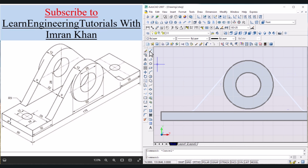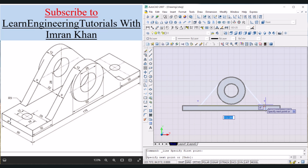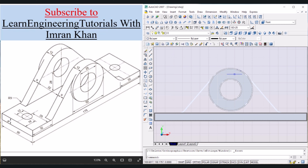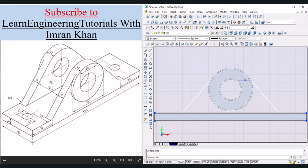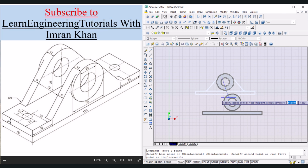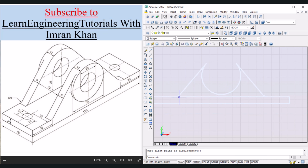Now click on this line icon, zoom in, find the end point of this arc, click and click on the end point of the other arc, click, press enter. Now let us remove the plane area and the 3D object as well. So click on the 3D object, click on this planed area, click on move, select any point and move them towards this side. Now remove this rectangle as well, so press delete.